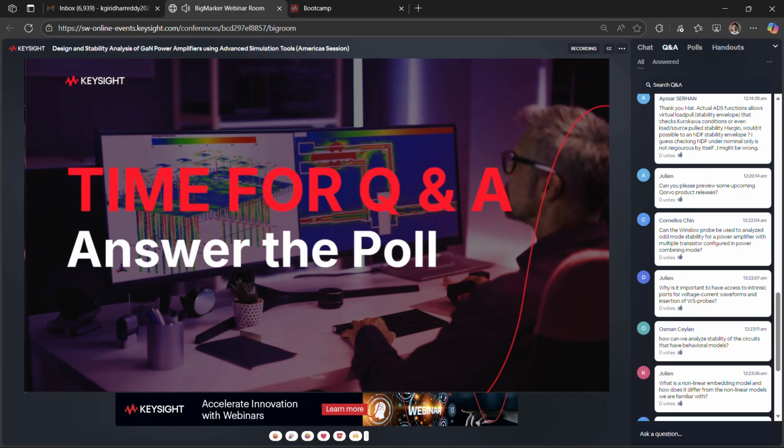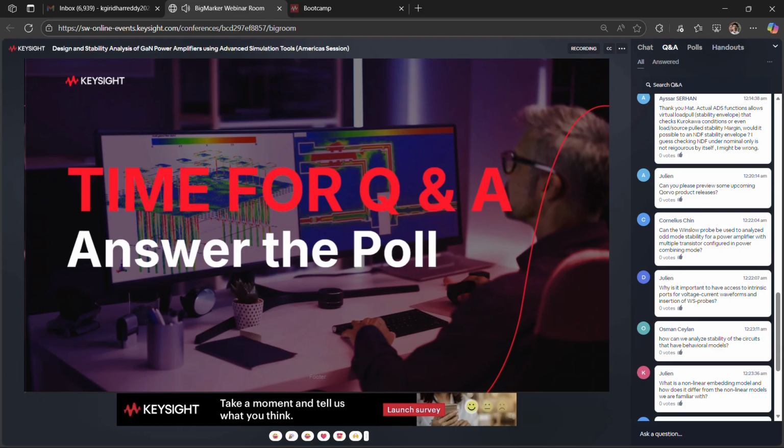If your circuit is relatively stable, if you have a very nice looking stability margin, then you can be confident that as things shift a little bit in your design process, or if you have process variation or things like that, you'll very likely continue to have a stable circuit. Whereas if you're right on the edge of an instability, any little change can trigger that binary crossing from 0 to 1.